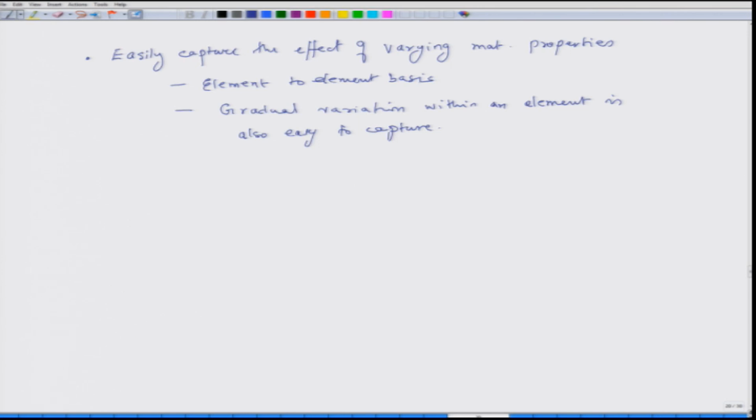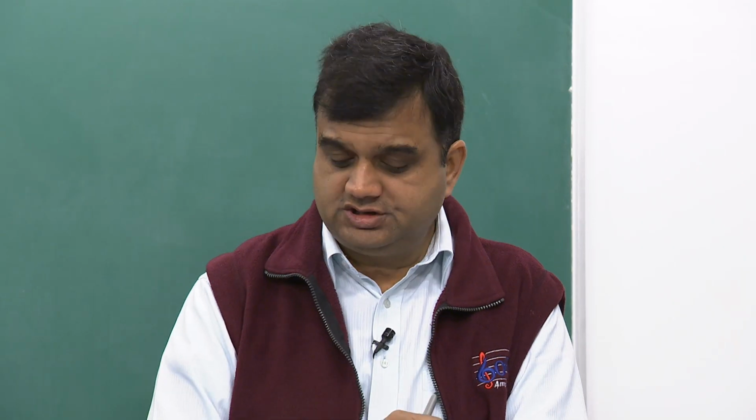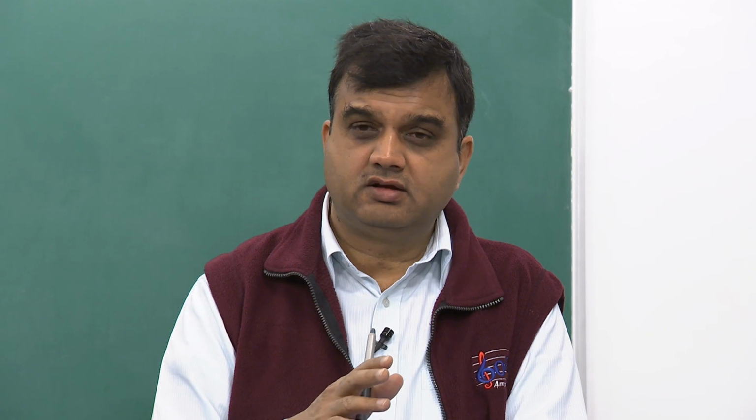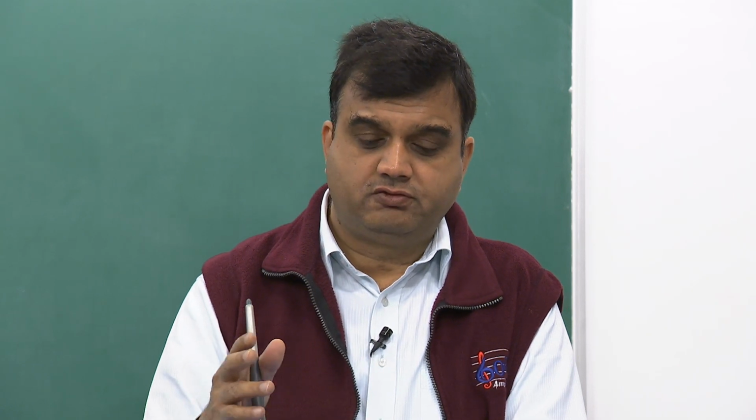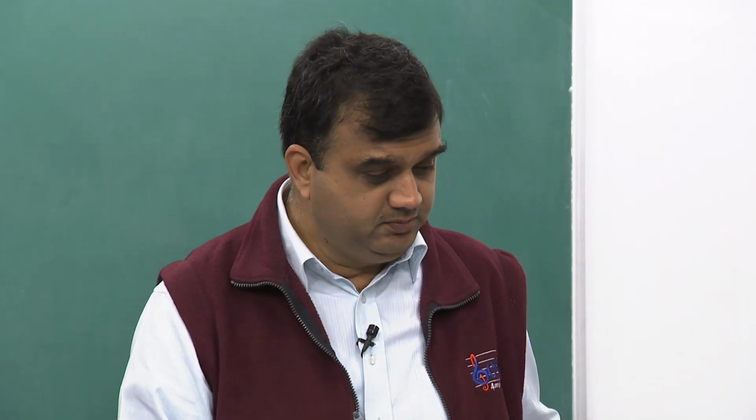As we calculate the error, we can plug in the varying material property, and because this variation is polynomial in nature, we can relatively easily integrate to find the weighted error within the element.